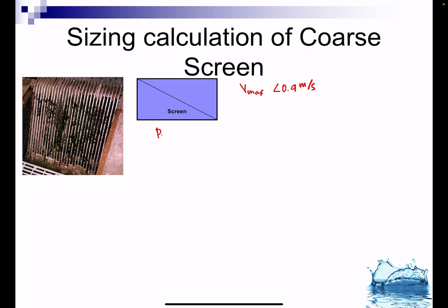From your peak discharge, or the average sewage generated per day. So the peak discharge, sabi ko kanina, if your assumption from the very start is that your average water supply is 10 megaliters per day, the average sewage generated is 85% of the 10 MLD. That is around 8.5 MLD. Convert MLD, megaliters per day, to cubic meter per hour, or the peak discharge could also be in cubic meter per second.